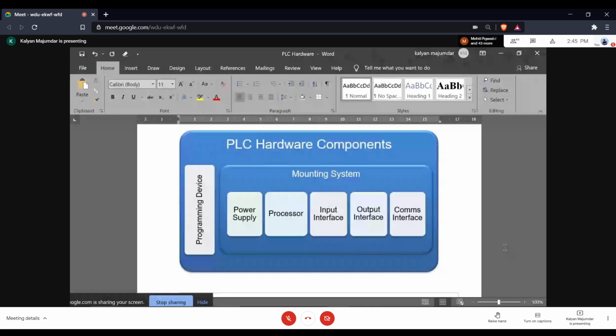Okay, fine. So we are basically trying to look at the various components of a PLC in terms of hardware, of course. The obvious components are, of course, a processor, and memory, both variants, RAM and flash. Third, you have a power supply unit, which takes the power from the mains and converts that into voltage levels that are required for the operation of your electronics.